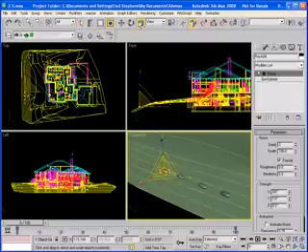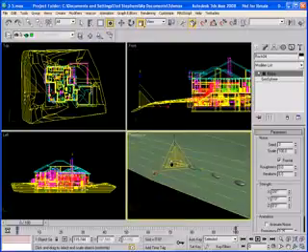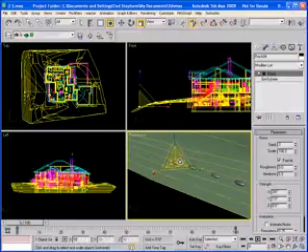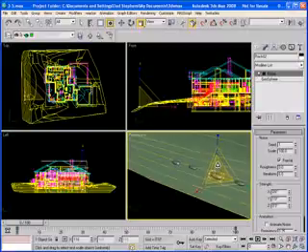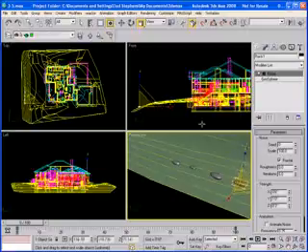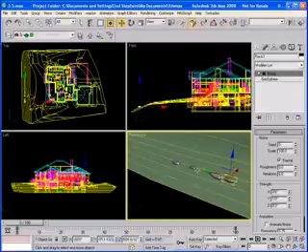And then now I'm going to go to my scale command. And each one of these I'm just going to scale up and down a little bit along some different axes just to make each one a little different size. So you can see in your scale gizmo, you can either scale it along one of the axes, X, Y, or Z, or you can go on one of those triangles and scale it along 2 axes. So I'm just randomly going in, changing the size of them. Again, trying to make this look more natural so that each rock is a little different. And then just using the move command, moving them together.